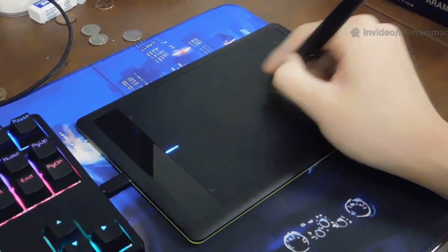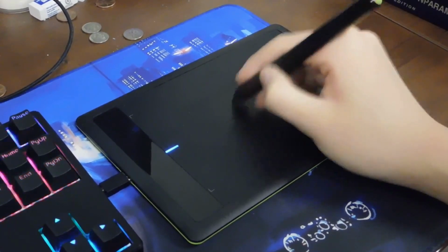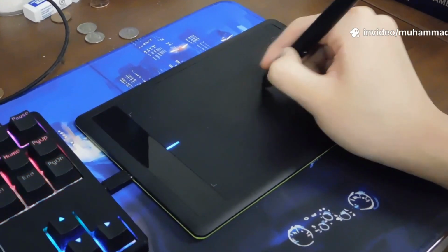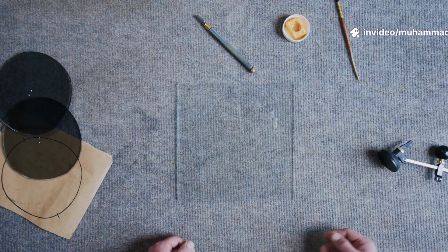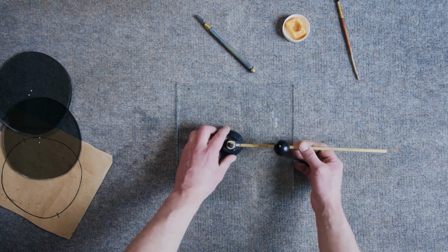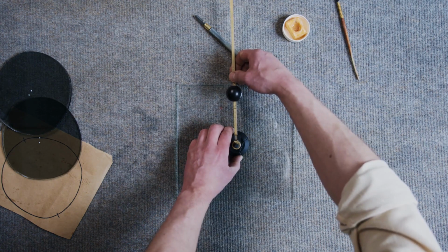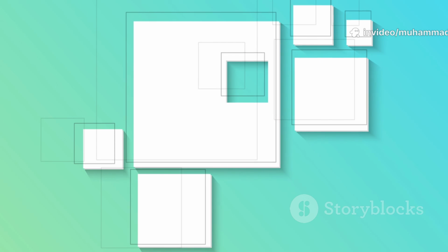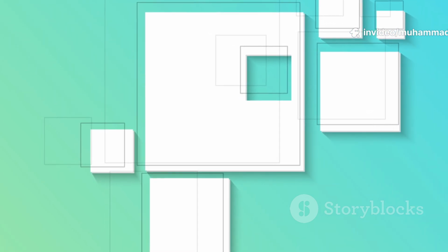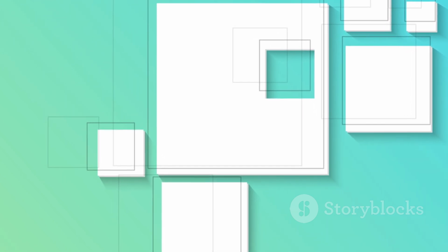Let's start simple. Select the rectangle tool, then move your cursor to the artboard. Click and drag to draw a rectangle of any size you like. Notice how the shape appears as you drag. If you want to make a perfect square instead of a rectangle, just hold down the Shift key while you drag. This keeps all the sides equal, giving you a neat, even square every time. Try making a few rectangles and squares of different sizes. Experiment with dragging in different directions and see how the shapes change. This is a great way to get comfortable with the tool.